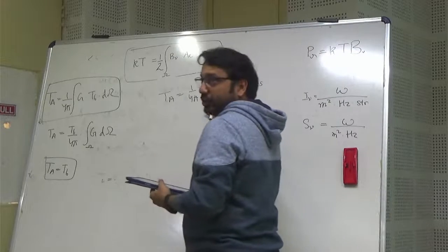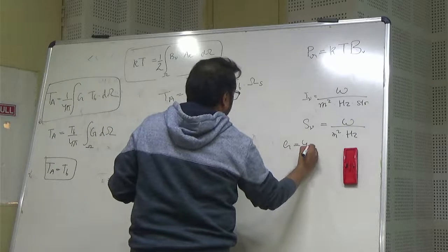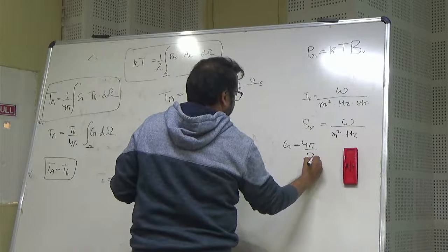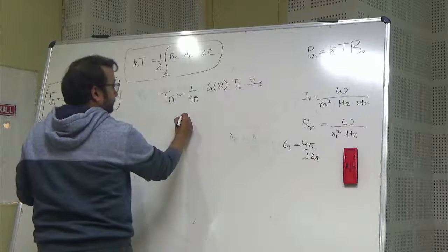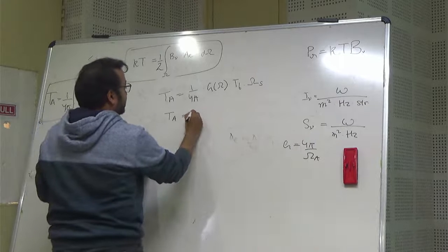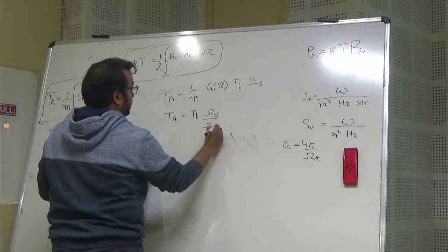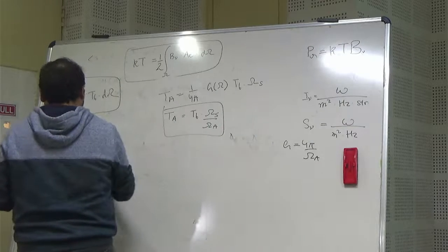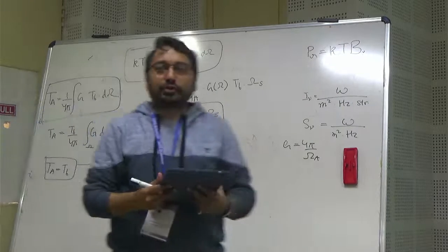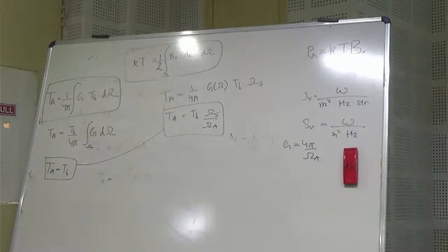And we saw that the gain and the solid angle of the antenna are related. So what you measure in case of a compact source is this. If you don't want to remember other things, fine, just remember these two. Which is, what does antenna measure when you have a diffuse structure, and what does it measure when you have a compact source?